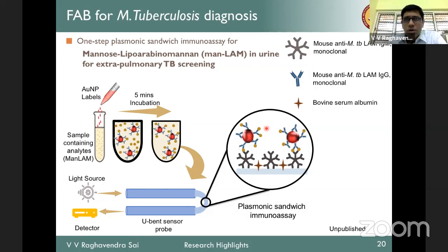On top of that, you typically have electronic circuits such as a constant current circuit, and on the photodetector side, good, simple amplifiers, not expensive. With that, you will be able to maintain the light intensity constant over at least 1 hour.